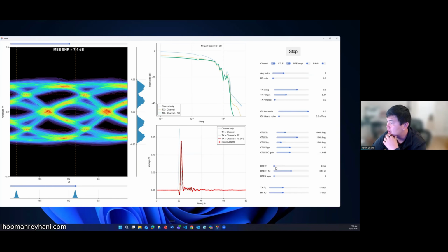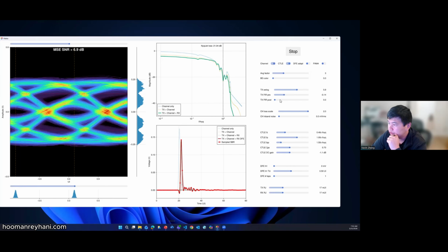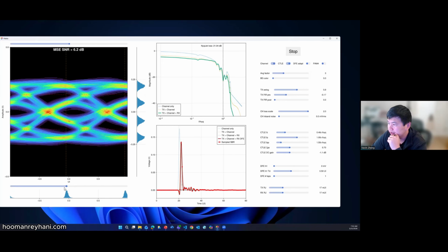So the only knob that we haven't exercised is the DFE, okay? There is a technique where we can use our sampling point. That's where the CDR comes in. Again, we're being the CDR now, but there are things you can do in the CDR to say, hey, instead of keep increasing this on the TXFIR, what I will do is I will move my sampling point forward a little bit. You can see that that effectively canceled this guy, right? And then what's left mainly is just the first postcursor. And that's what DFE is very good at canceling.